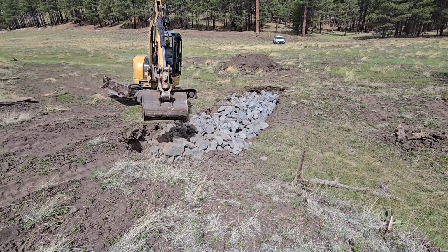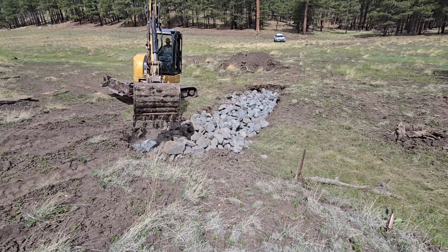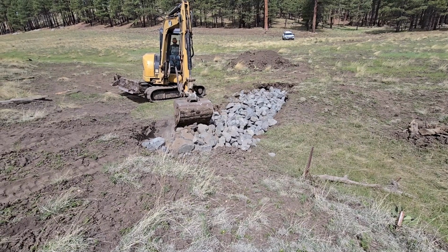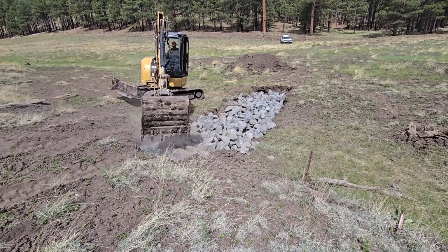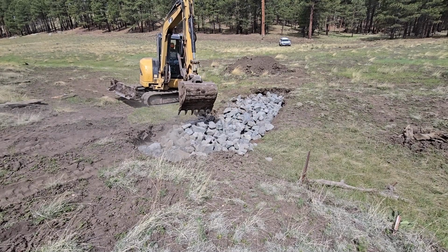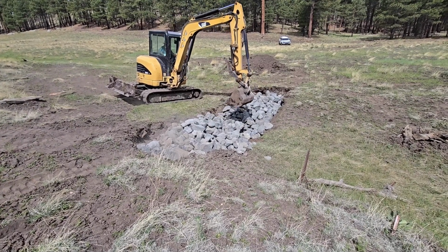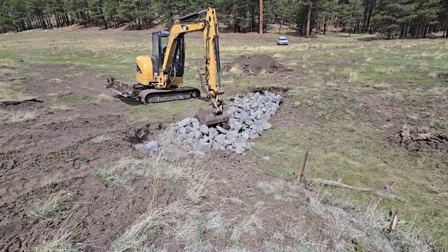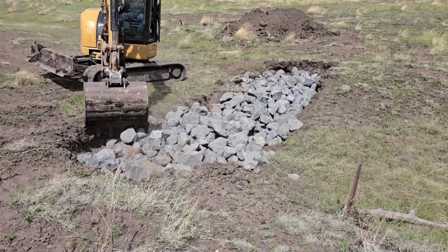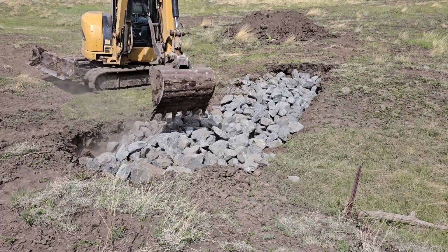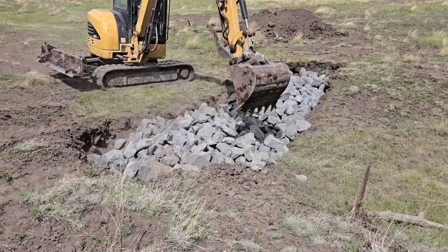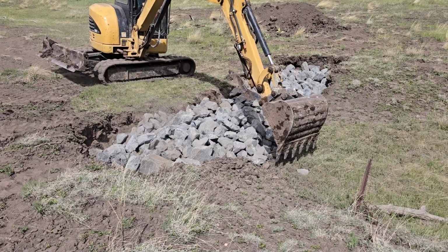Don uses the bucket on the excavator to move the rock into position and to shift the rock so it fits tightly together. The surface of the rock is shaped to match the slope in the valley at this location. A shallow dip is placed in the center so that water will flow over and not around the rocks. The bucket is used to compact the rock tightly together so there are only small gaps between the rocks. You can see how some of the rocks are pushed down 6 inches or more when pounded on with the excavator. Don takes his time and is very thorough in fitting and shaping the rocks so they won't settle.